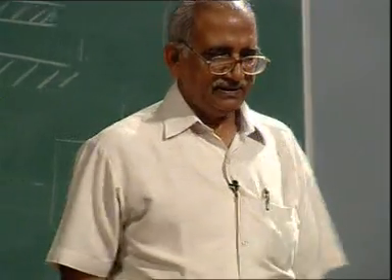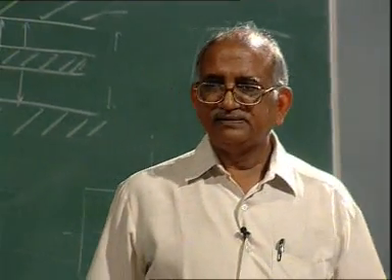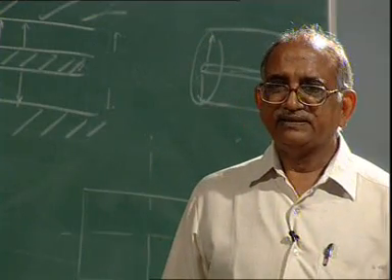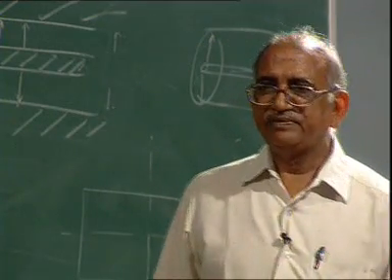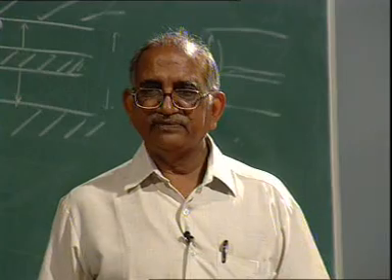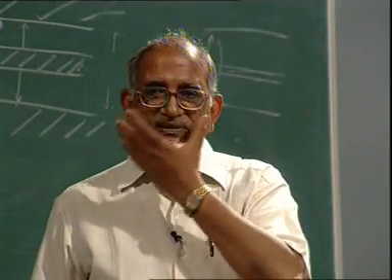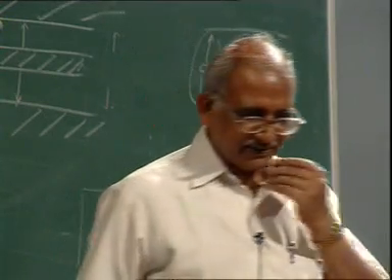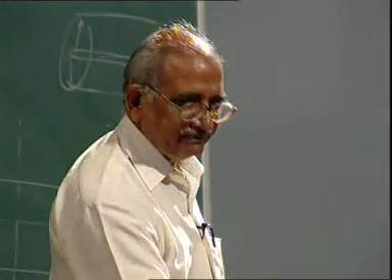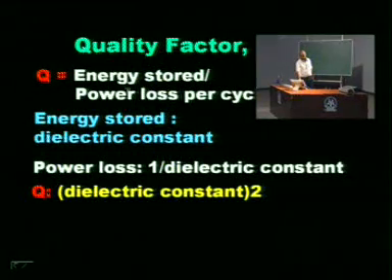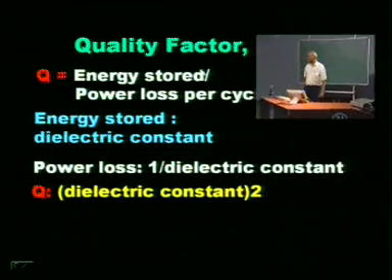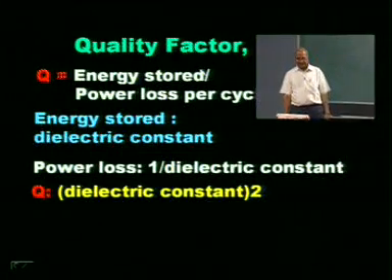Okay, if we calculate the quality factor just like any resonator, that gives you all the information from the circuit point of view, that will tell you about the bandwidth, etc. And we know that the quality factor, just like any resonator, we define as the ratio between the energy stored and the power loss per cycle.